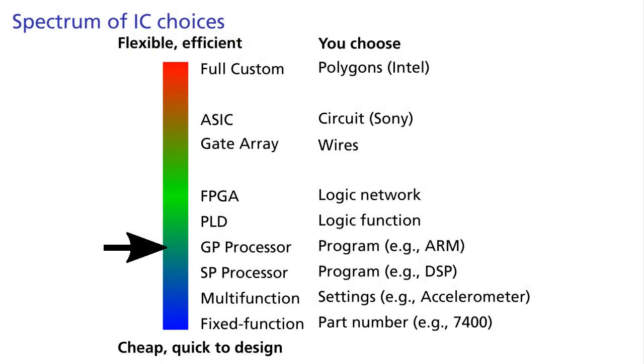The 386 and the SPARC represent two fairly distinct points on the general-purpose processor spectrum, but they have a common goal of running most workloads with similar efficiency. While that is a laudable goal for, say, a desktop computer or even a cell phone that will be expected to run many different kinds of applications, many processors and embedded systems will only ever run a single application. As such, it seems like you should be able to develop a far more streamlined processor that's only good at certain tasks and slow and awkward for others.